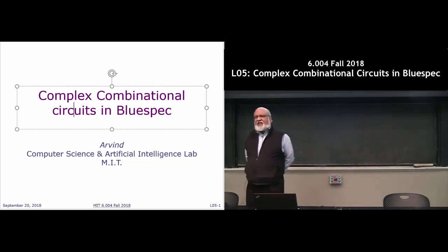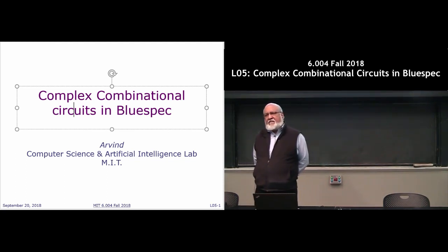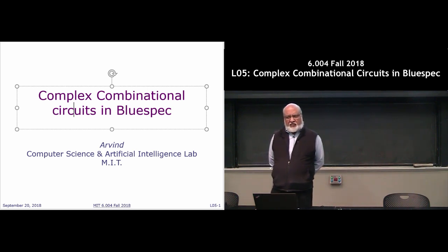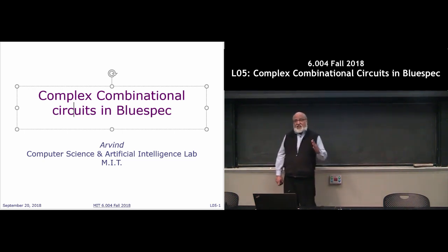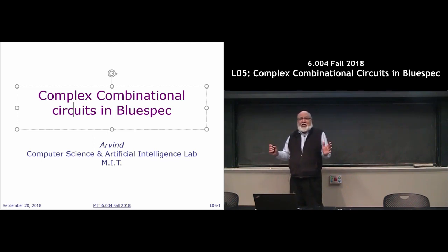If I receive an integer and I'm trying to put an array of bits in it, the circuit has no place where it checks that. You should not even think that I'm storing it anywhere. If I say x is vector so and so, all I've done is give it a name, right?